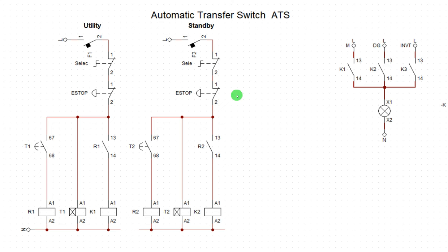So you're going to simulate it now. I put it on. Okay, it's not coming on. There's an issue here. What is the issue? We don't have neutral here, so let's put in our neutral.